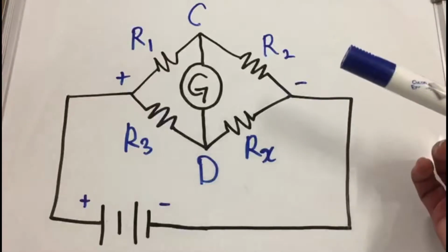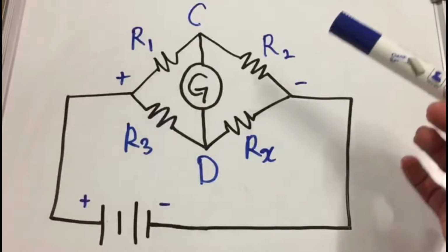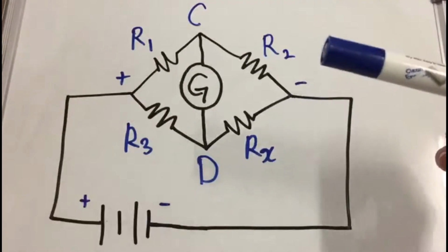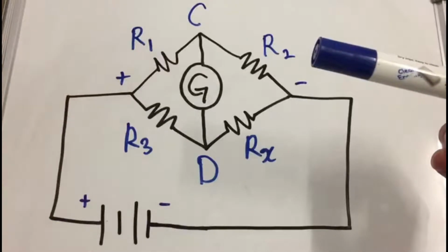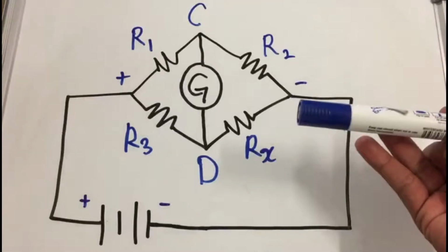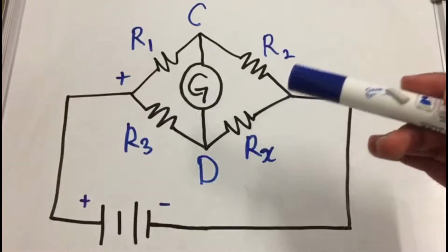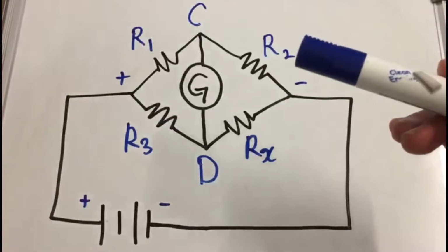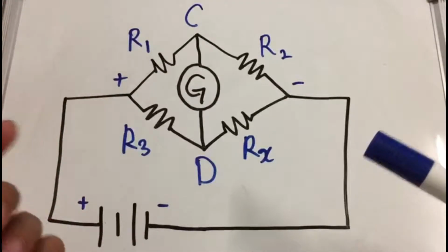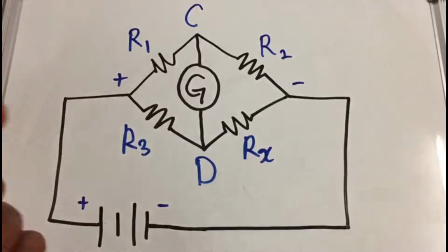Using the Wheatstone bridge, LDR, operational amplifier and some standard resistors, a circuit can be constructed to output a high or low level signal which is dependent on a selected threshold. An LED will be used to determine the state of the system. In practice, the Wheatstone bridge is seldom used merely to determine the value of a resistor. So I will pass on to Akashah to explain our project.